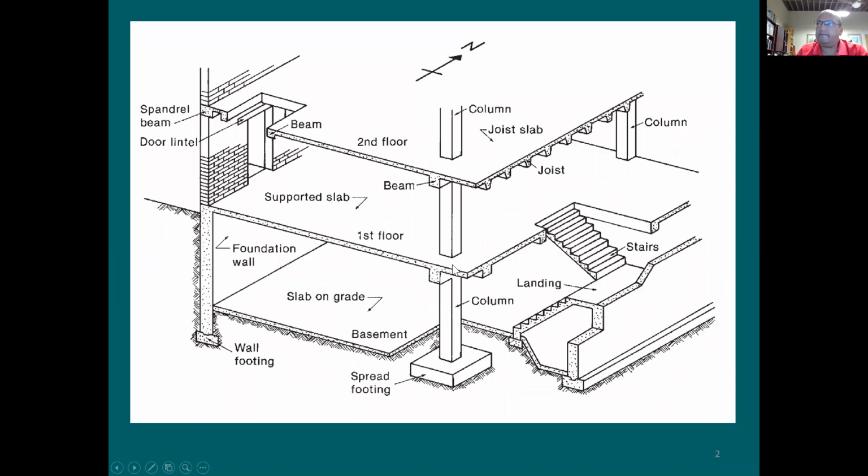Now a question. Do you think that the load is coming here from the top? Is it going to this slab, to the first floor slab? Or just bypassing it through the column? Because when I design the first floor slab, I need to know what loads I'm gonna be designing it for.